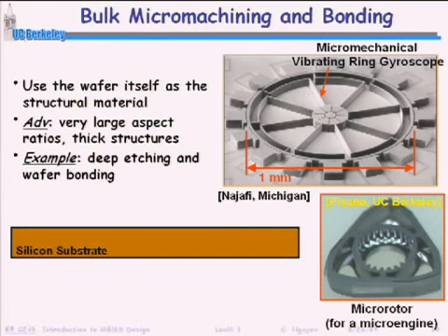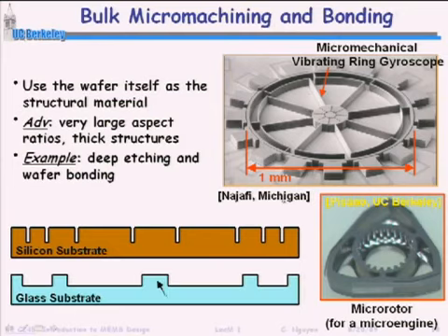You then do a similar thing to a glass substrate, where you etch, say, anchor points for this structure. So this kind of defines a structure. You can't see it yet. You then put some interconnects on this glass substrate, flip the wafer over and bond it to the glass. This is done through a process called anodic bonding, where you can get things bonded such that they stick with very high strength.